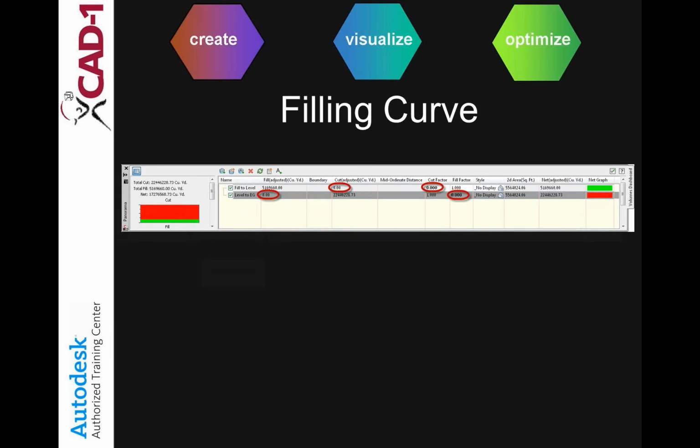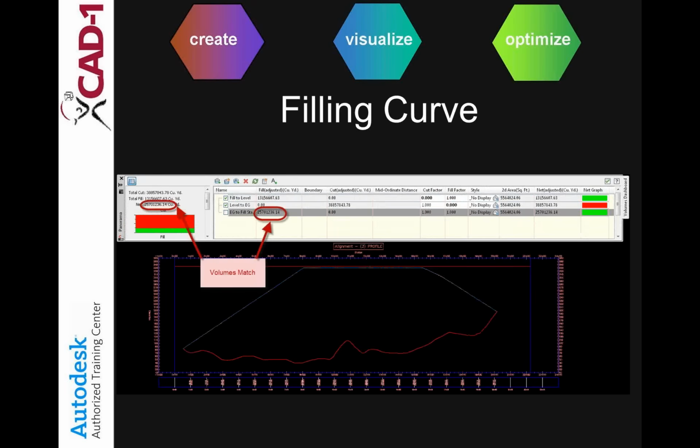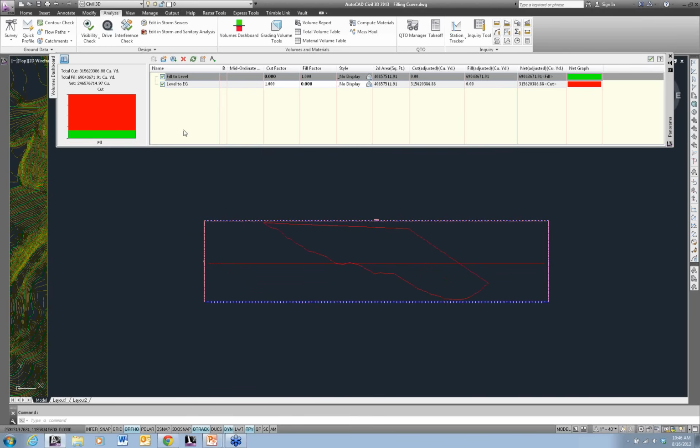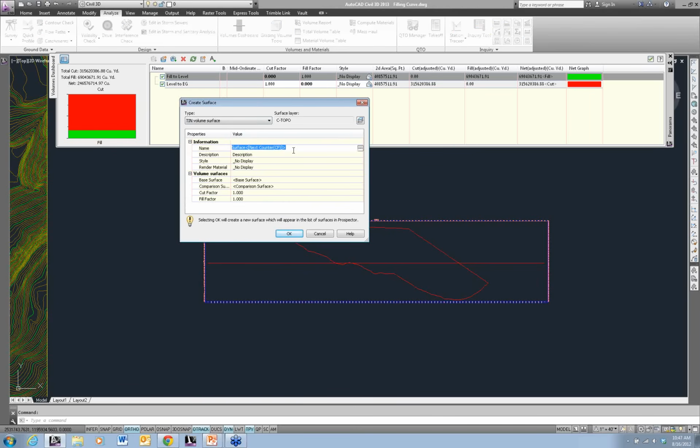Now, any engineer out there, you just don't stake your license on something that the computer spits out, right? You want to make sure that this works. So what we're going to do is create another surface in here, another volume calculation that just computes the volumes between the two. All right, so I just want to know the total volume once this thing is completely filled.